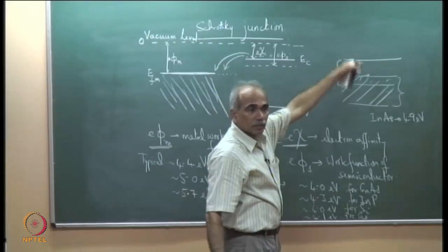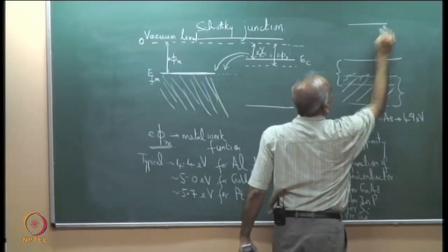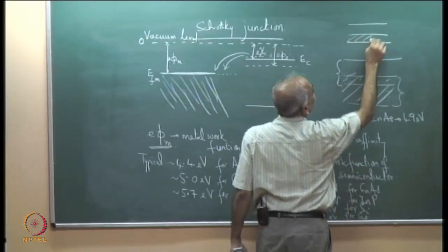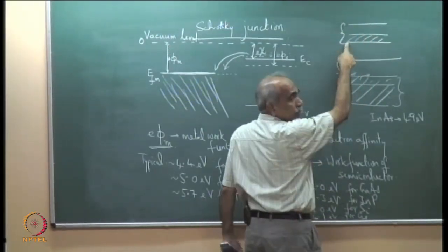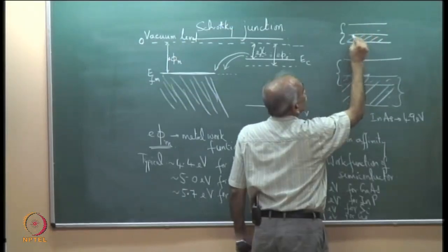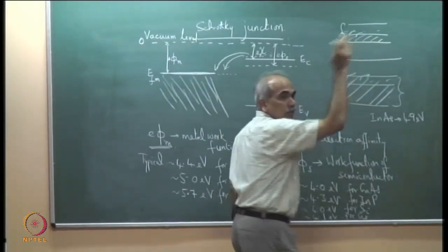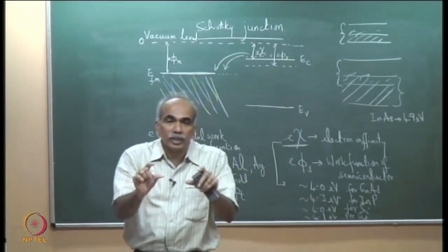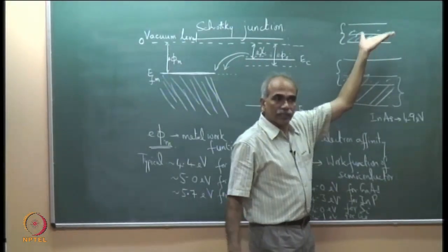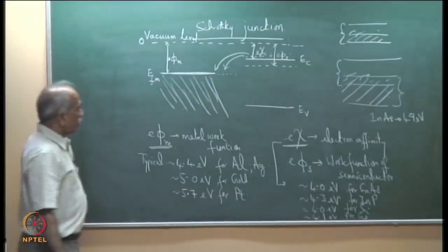This is overlapping bands. Or you could also have only a half filled band, which also means the same. Half filled means this is all filled, this is one band, but these are all empty. The electrons can easily go to the empty state and move. With a small application of potential, they can immediately move. That is why the conductivity is very high.